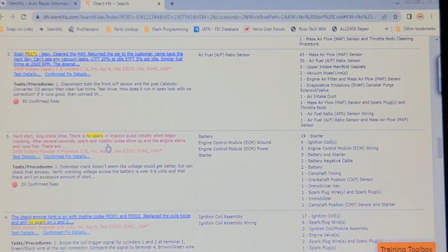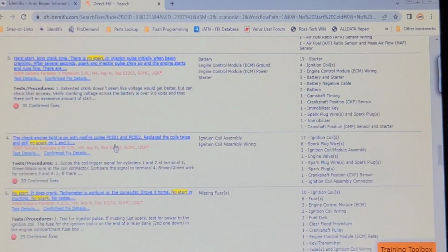So I plugged it in. Going to warm it up and see if it'll start. It cranks fast enough, in my opinion. It should start. I wonder if this is a magnetic pulse generator. I'm going to get it warmed up and get it in the shop and put some test probes on it so that I can check for injector pulse. And we know that there's no spark from the coil, and it's a new coil, and I can't see a new coil being exactly the same as the old one.